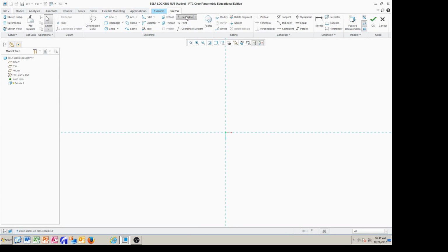And I'm gonna place a center line on a y-axis and x-axis, because I'm gonna use the palette to place the hexagon at the dead center here. So I'm gonna put a point in here. All right, that is because we're gonna do the coincident. We're gonna use the constraint called coincident. So it's better to put a point at the intersection.